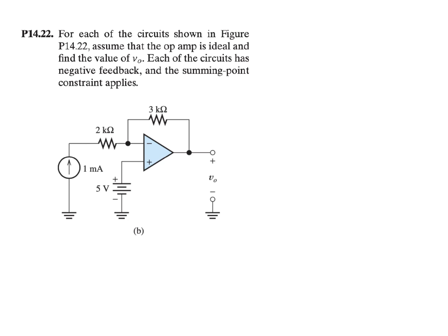Question B. Similarly, we need to find V out. V out is here. Let's see how many nodes we have. Again, we only don't know V negative. So the only unknowns are V negative and V out. We can see that V negative is the same as V plus for an ideal op-amp. And for V plus, we have a voltage source here. So this is 0 volt plus 5 volt is 5 volt. So we have V plus is equal to 5 volt. So now V negative is also equal to 5 volt.